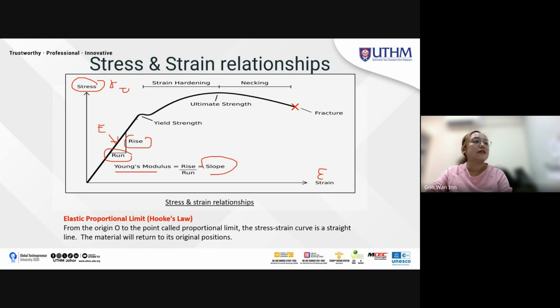This is the typical stress strain curve for concrete or the steel bar. Imagine you pull a material until yield strain happens. When the yield strain happens, you go down a bit, then going upward. This is the area of the elastic stage, where the material will still go back to its normal shape.